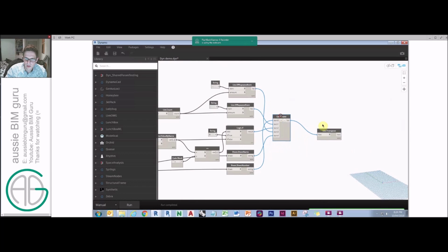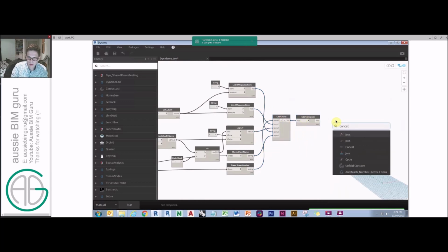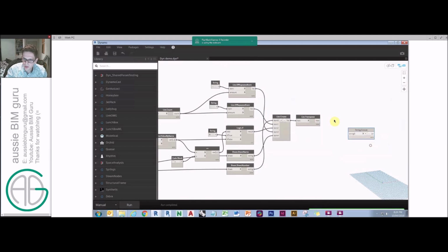And the way we need to deal with this now is run a concatenate function, which will join all the pieces in that list. So if I run that, you'll see that I end up with 6 things that are essentially my sheet numbering convention. We could say that we actually want to do, so let's say we'll do underscore instead. There we go. So that's a pretty good convention right there. So these essentially are our sheet names.